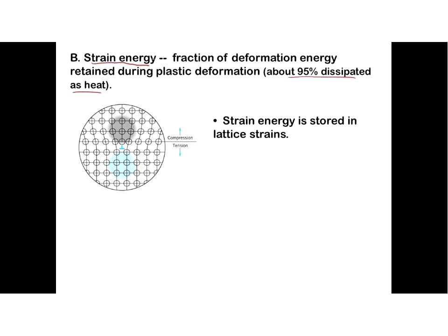And that strain energy is schematically shown on this picture, on this top-down view of a crystal structure or crystal lattice that has an extra half plane of atoms inside of there, which is an edge dislocation. And we note that at this point here, if we were to draw a line in between where the half plane is and where the half plane ends, the radius between atoms is less than the equilibrium spacing R naught.